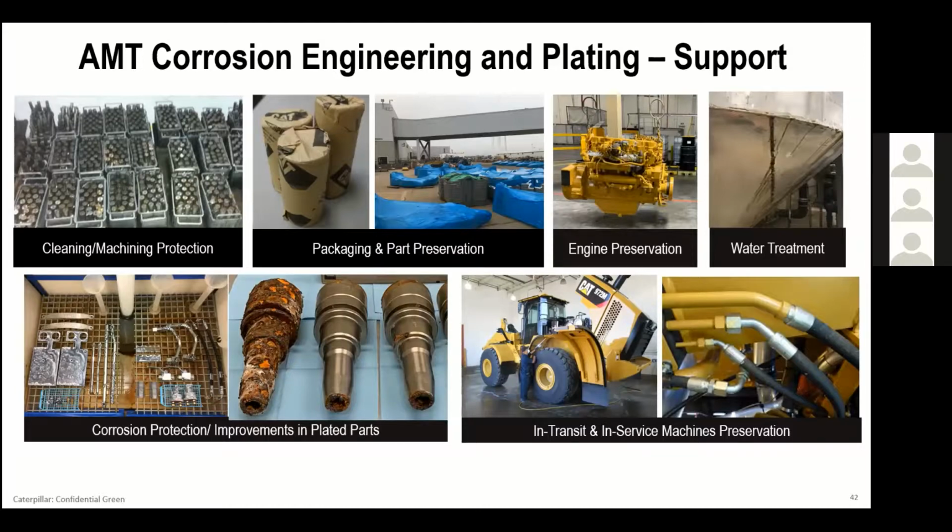And then, once you start, it's like the human body, there's just not one thing that's occurring. Generally, when corrosion starts, especially in something that's seeing a high volume of water, additional things could be occurring, such as high bacteria, sulfur-reducing bacteria, to increase those rates and cause other things to occur.